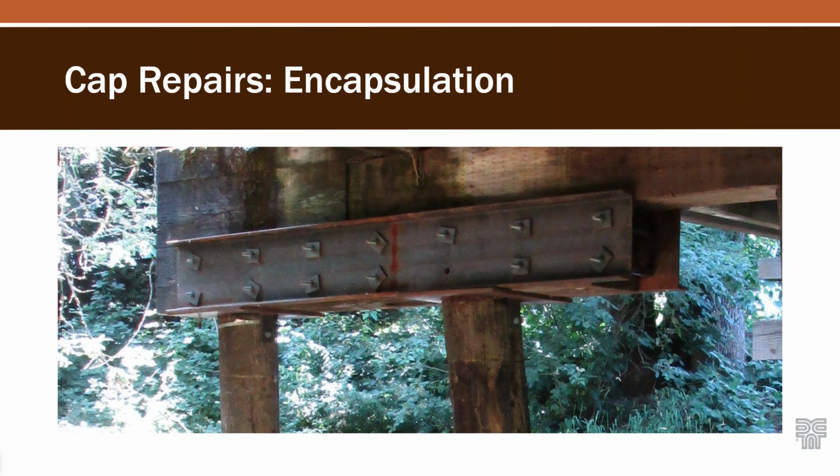Depending on the details for this, this one here was intended to be more of a temporary repair, I believe, because it doesn't actually replace or make a connection directly to the superstructure above it. So it's not actually taking the load directly from the girders or the slabs up above. They still have to work their way through all the timber to get to it, and then from the timber cap into the channels, and then from the channels down to that steel plate into the pile. So it's a unique load path, but it certainly provides a lot more capacity than what was there before.